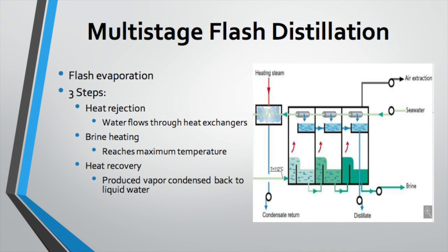Okay, so we're going to begin by talking about multiple stage flash distillation. So MSF is a seawater distillation process based on the principle of flash evaporation. Flash evaporation is essentially when the incoming feed stream of seawater is heated and evaporated and then condensed to produce the distilled water. So the process operates in three distinctive steps: heat rejection, brine heating, and heat recovery.